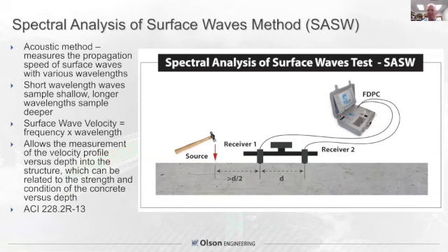So the next technique we used is very good for evaluating distributed cracking in concrete, as well as depths of perpendicular cracks. And we've used it in special applications on bridge decks as well, that you'll hear in a bit. But this is called spectral analysis of surface waves. And you impact the concrete with two receivers in a line. We use a bar that we make in Olson Instruments and connects to a data PC that we make as well to take the data, and does a bunch of different ultrasonic, sonic tests. But you measure the wave propagation of a surface wave between the two receivers.